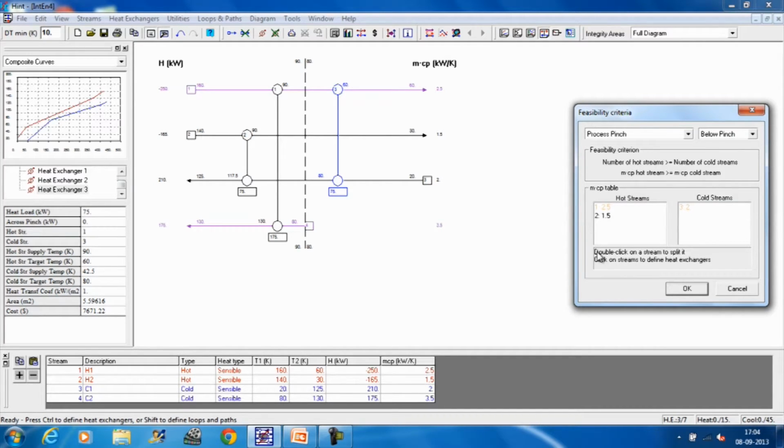Now, we have to little bit analyze these rules. These rules are for pinch heat exchangers. That means, for the pinch heat exchangers, these rules are sacrosanct. That means, they have to be followed very rigidly for pinch heat exchangers. But if it is away from the pinch, these rules can be slackened. That means, somewhat we can slacken this rule and put the heat exchanger. The only criteria is that it should not violate delta T minimum criteria.